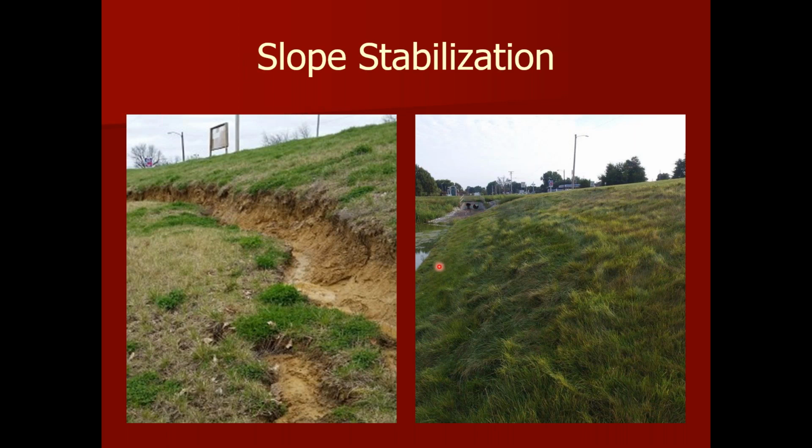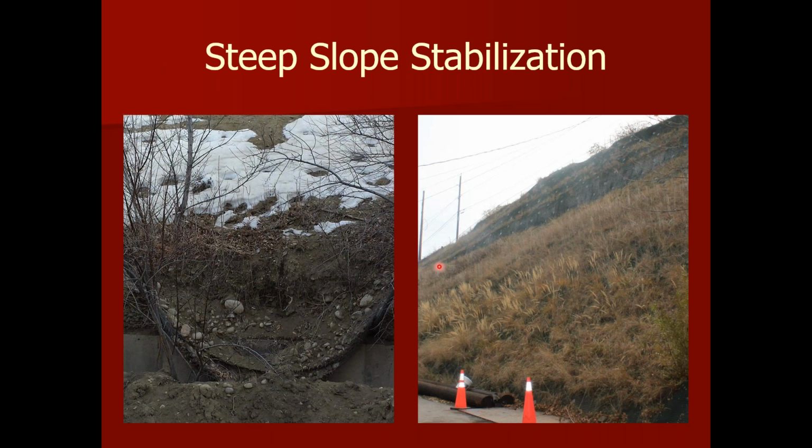this structure. Steep slope stabilization is really a geotechnical issue. Of course, there's some hydraulic component with that. Typically, it's just with rain runoff. But the idea, again, is to be able to use the tensile properties and the strength of a TRM in conjunction with anchors in many cases to provide that enhanced stability on steep slopes and prevent the toe, as you see here on the left, getting washed out or pushed out, as most commonly is the case because of poor water pressure within the embankment itself.